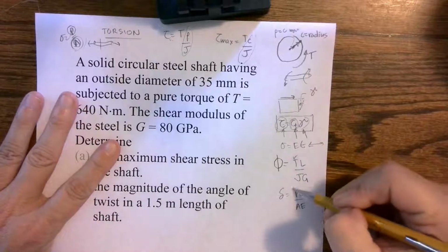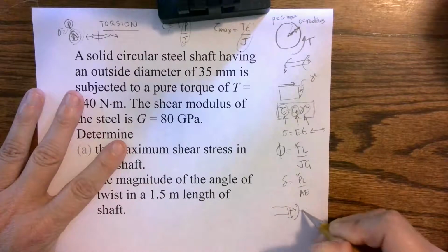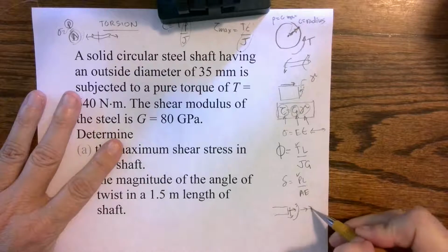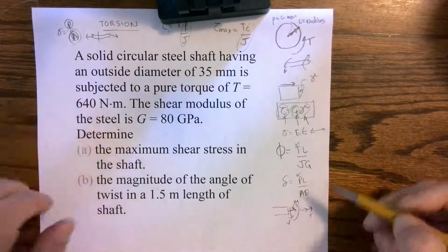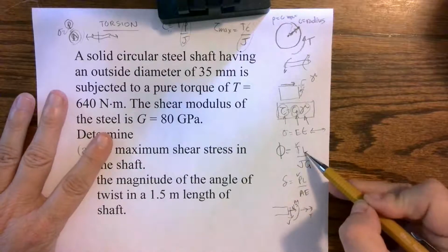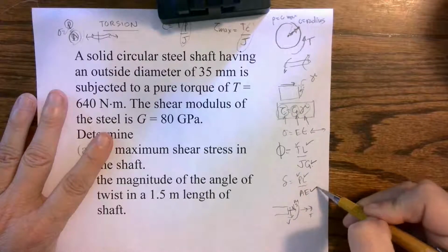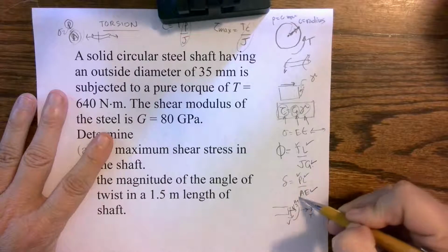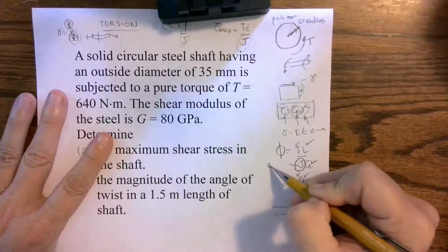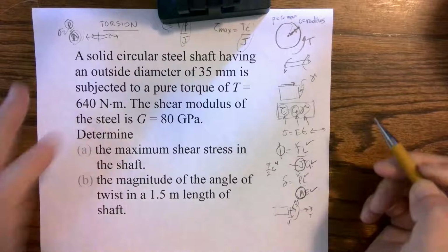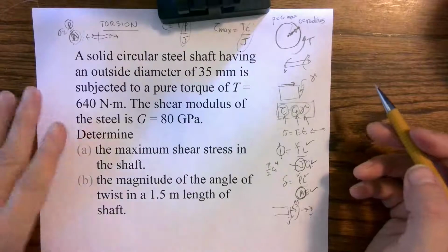We can see they both are internal forces, so this comes back from statics. If I were to figure out internal forces, and we don't really look at torque in statics, but we could look at torque, we have an internal normal, torque, moment, and shear. So we're dealing with this internal resisting torque. Length, just like what we had with delta. G is the equivalent for shear as E is for normal. Cross-sectional property, so geometry, J, polar moment of inertia. It is also a cross-sectional property. Remember, C is radius. So the equations are set up very much the same.